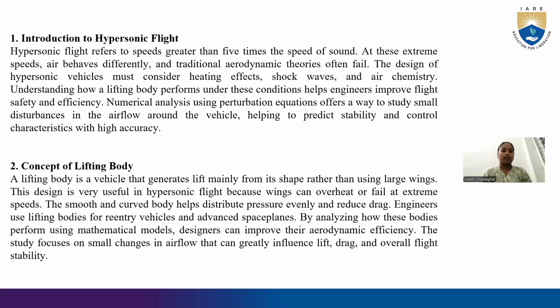Concept of lifting body. A lifting body is a vehicle that generates lift mainly from its shape rather than using large wings. The design is very useful in hypersonic flights because wings can overheat or fail at extreme speed. The smooth curved body helps distribute pressure evenly. The reduced drag energies use lift bodies for re-entry vehicles and advanced spaceplanes.